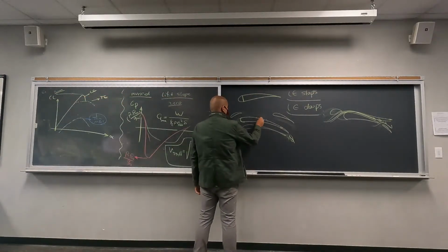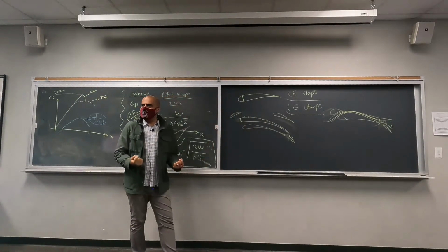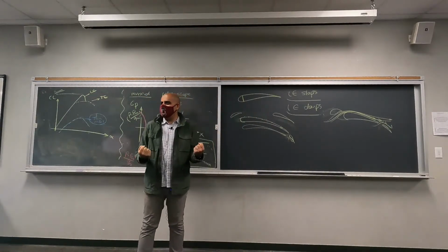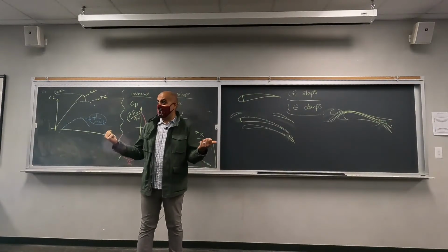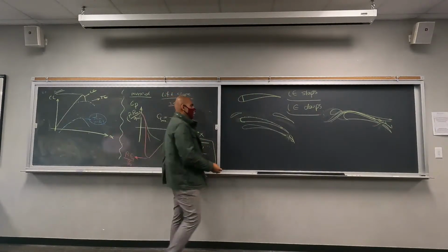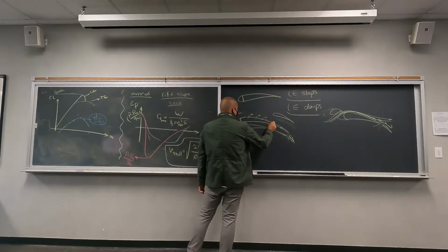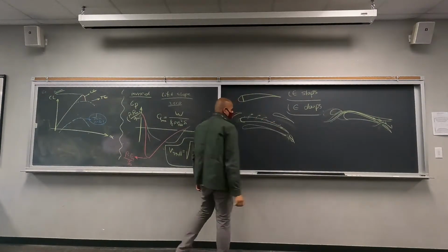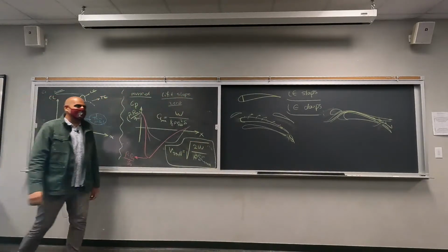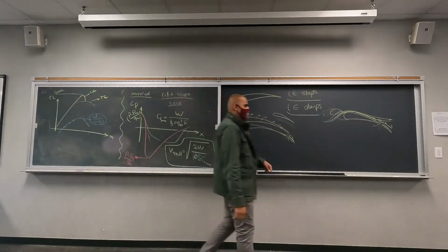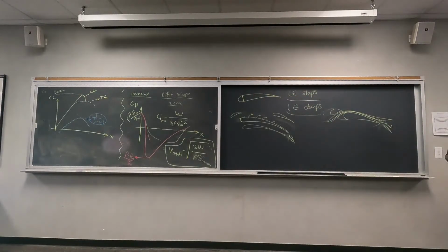But we can also have suction. Right? We can suck the boundary layer in. When you're sucking the boundary layer in, there's no space left for the flow separation to happen. Or we can have some jets, doing the reverse of a suction, which is not a very effective way of doing this because you are introducing some pressure as well, which is not a very desirable condition.